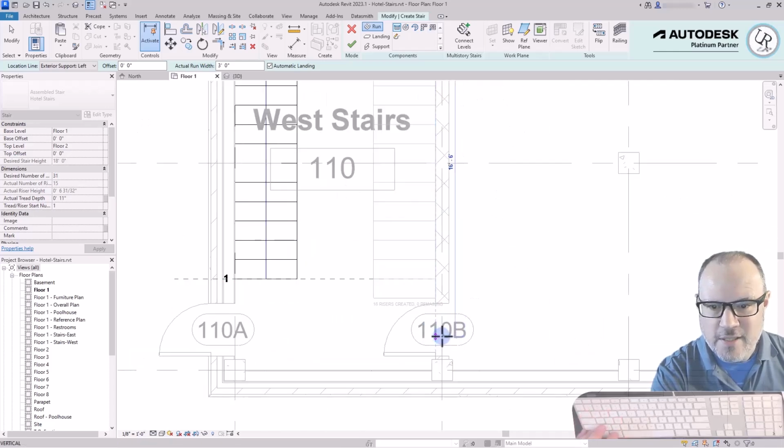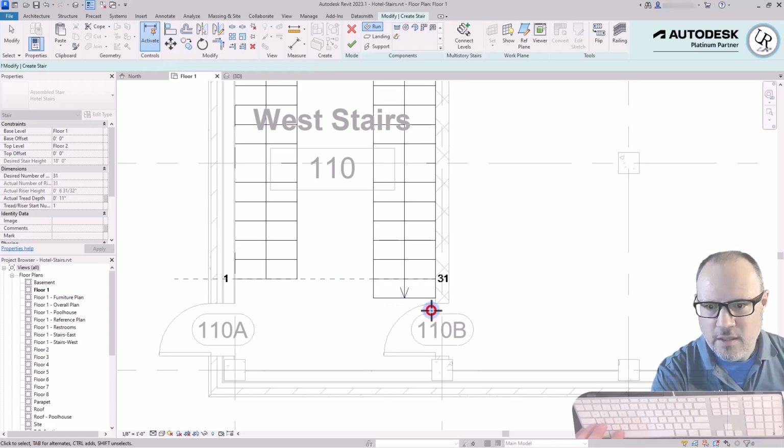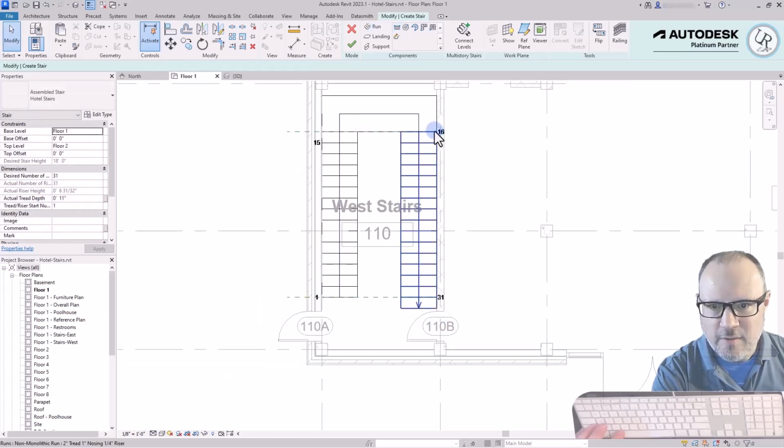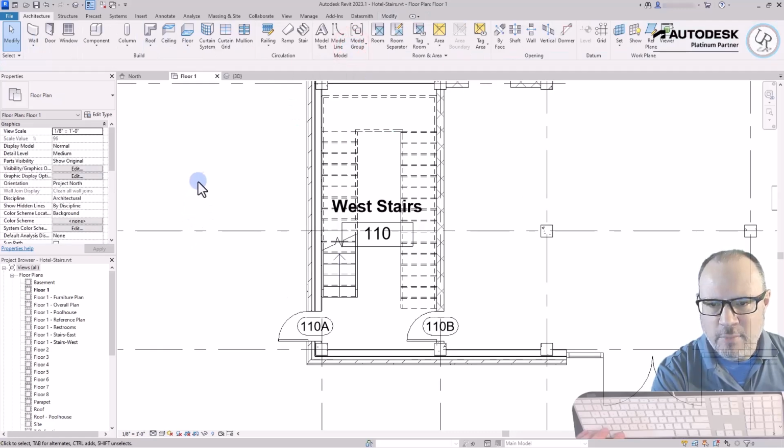And then run the rest of the stairs up to this amount. It says 16 more risers and 0 remaining. Notice how the number is changing as I increase the length of the stairs. That is placing the number of risers at a time up to 31 risers total for 18 feet floor to floor height. Left click and it places that from riser 16 up to 31. Then go up to the Modify tab and choose the green check mark to finish, and that completes the stair creation.